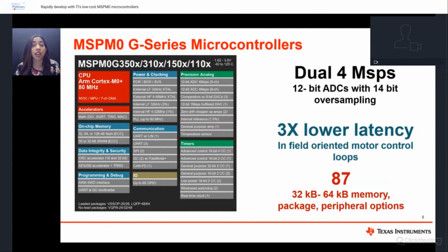These devices also have other advanced peripherals, such as Math Accelerator to enable fast and efficient math operations, reduce calculation time of division, square root, and trigonometric calculations. And MSPM0G also has CAN-FD for automotive use cases. Both MSPM0L and MSPM0G devices provide a variety of analog features to support different system designs.